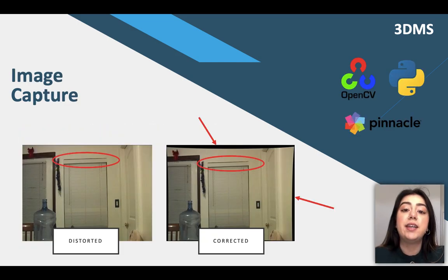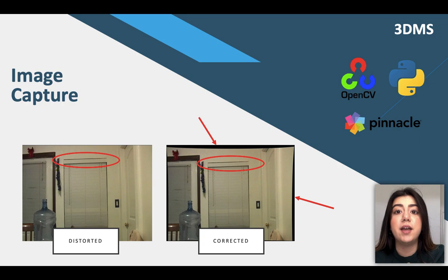Along with the PTZ and camera control function, the video capture capability was a necessary next step to take pictures from the PTZ camera. Using a Python-specific module called OpenCV, the live video capture and picture storage function was made possible. Using a device called Dazzle by Pinnacle, the PTZ would connect to a computer using an analog composite video source via USB. This feature would then allow the PTZ to be recognized by the computer and utilized in the Python script.